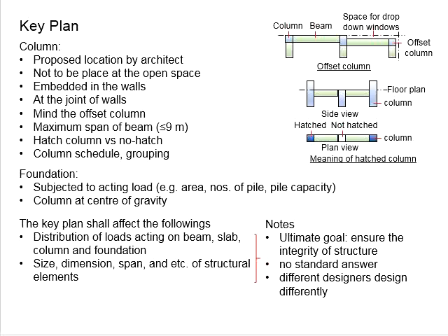As far as local practice is concerned, timber piles are not applicable now, especially for building works. Infrastructure probably, but for buildings definitely not. That leaves you with two main options, which are either RC piles or spun piles. The RC piles normally have lower capacities, and the spun piles normally have higher capacities.